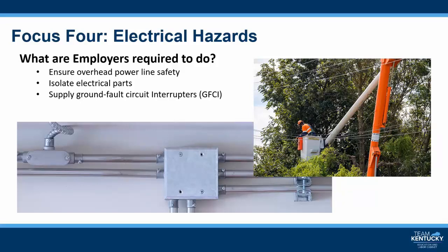conductors enter shall be effectively closed. Unused openings in cabinets, boxes, and fittings shall also be effectively closed. All pull boxes, junction boxes, and fittings shall be provided with covers. Metal covers shall be grounded. In energized installations, each outlet box should have a cover, faceplate, or a fixture canopy. Covers of outlet boxes having holes through which flexible cord pendants pass shall be provided with bushings.